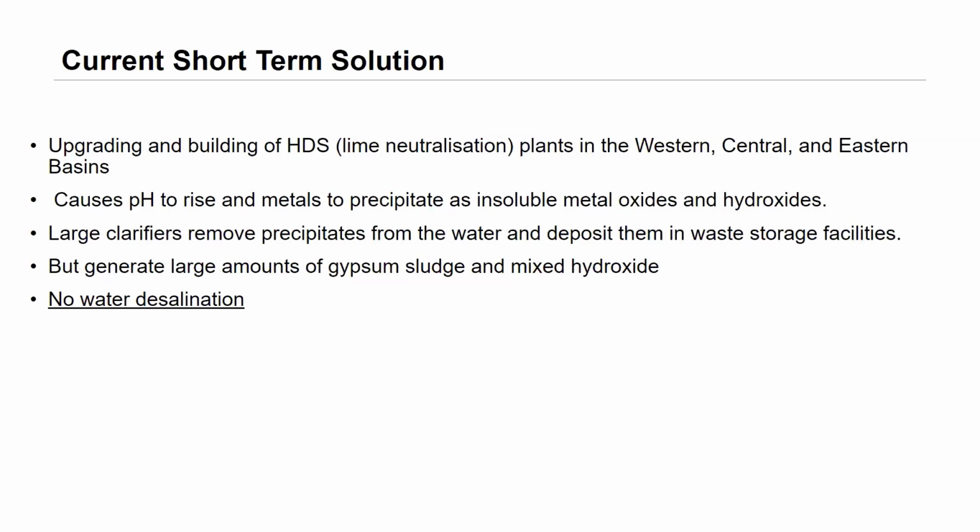The challenge of that proposed solution, though it is very well established and quite cheap, or at least the process is well understood and extensively used, not only in South Africa, but in Australia and also in Canada. It's quite an old process, flexible as well, can be used for small companies, but also for large-scale companies. It has a challenge in that it does not provide a desalination of the acid mine drainage. And desalination is a serious threat for the water system, particularly the rivers and the streams in the country.